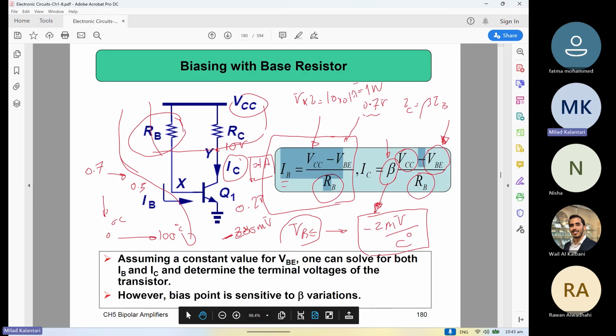And this dissipation actually increased the temperature of the internal circuit, right? So you turn on the circuit. Let's say we call it the junction temperature because it's a semiconductor with some junctions inside, right? Junction diodes. So you turn on the circuit. Initially, the circuit is cool, right? Initially, you start with 10 volt and 0.1 amp, and you are dissipating 1 watt inside. What will happen?